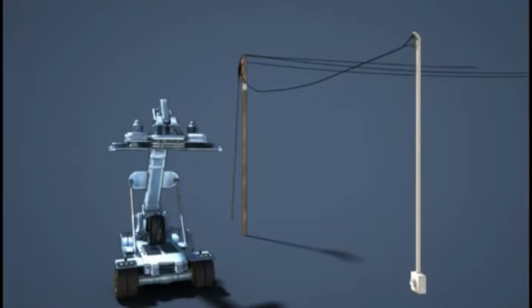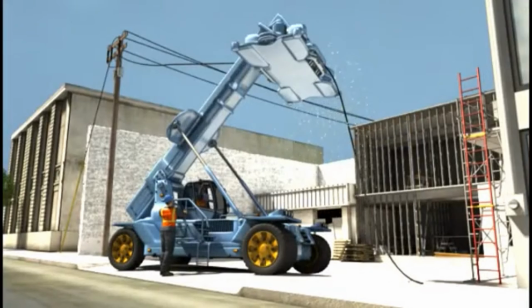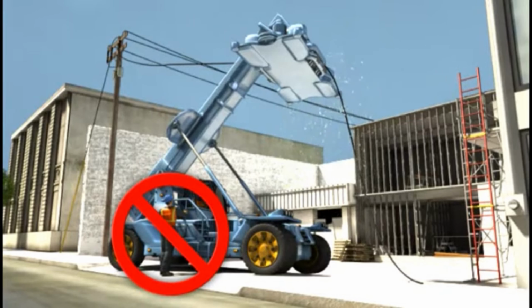As a basic rule of thumb, just remember that crane and rigging components should not come within 10 feet of a power line. If a coworker appears to have been injured by an electric shock, do not enter the area or physically contact the person unless you are sure there is no danger of being shocked yourself.